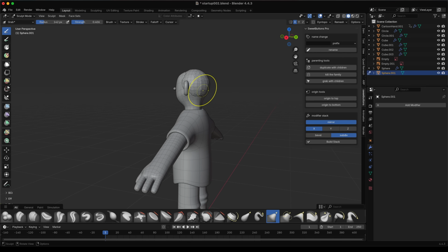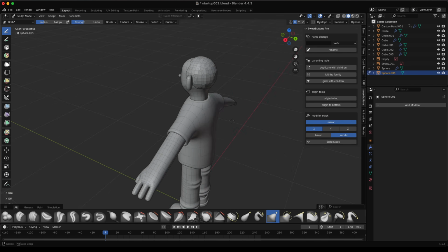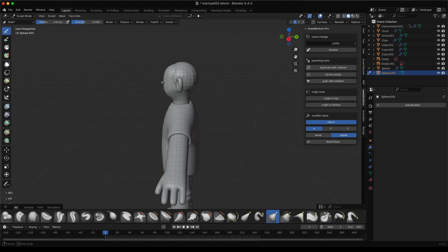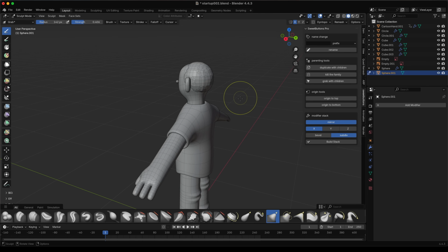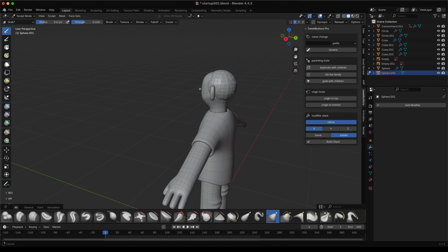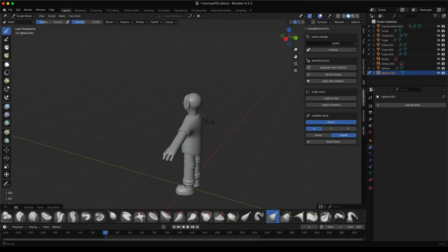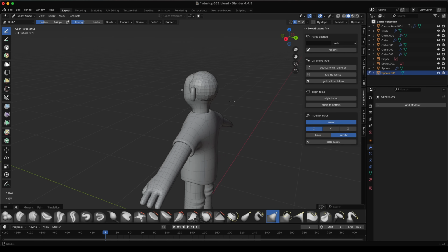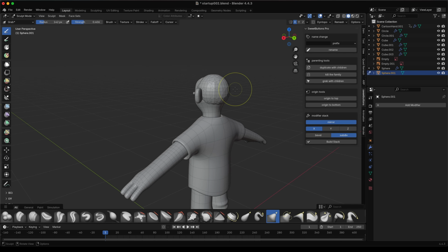Okay, so I'm just going to go through here, and if you are orienting yourself to the 3-button mouse, if you've never done that, Alt and click and drag with the pen will orbit, Alt Shift will pan, and Alt Command or Control will zoom. So there you go. That's the sculpting crash course there. F, of course, is going to change the size of your brush. Shift F is going to change the intensity.